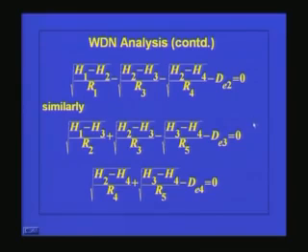So, the number of equations depends upon the number of nodes I have in the system and the number of reservoirs I have. The number of reservoirs I have means I know the reservoir water level. If I know the reservoir water level, then for the node connected to that reservoir I will know the head at that node. So the number of equations is the number of nodes minus the number of reservoirs. Let us say in this particular case I have 4 nodes and 1 reservoir. So the number of equations is 3 equations in 3 unknowns, and these can be solved for H2, H3 and H4.